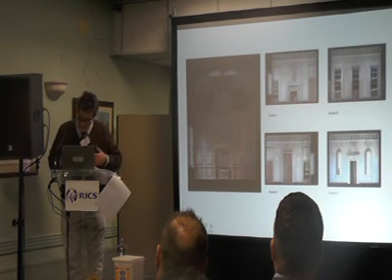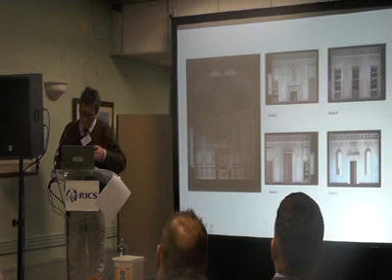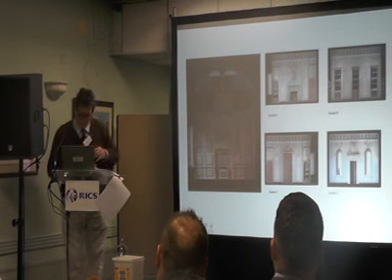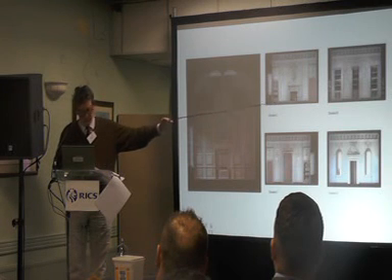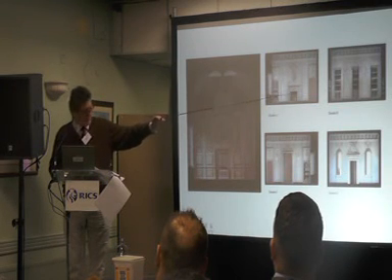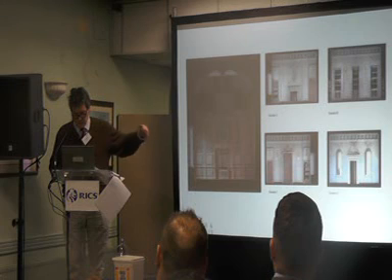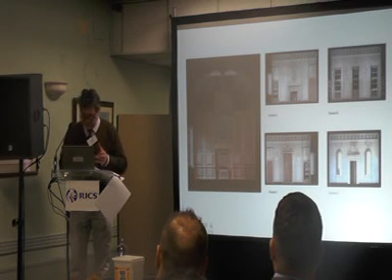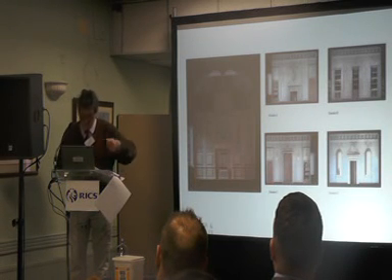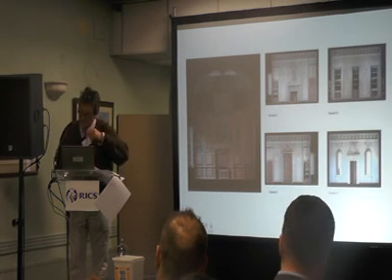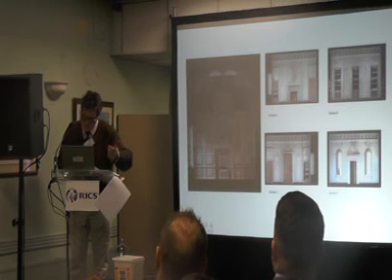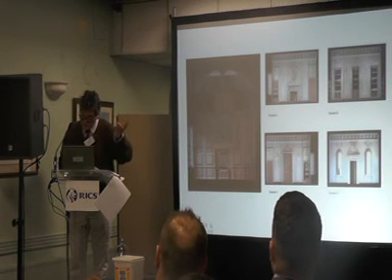If we scan that in 3D before we start work, we've been working above these plaster rooms. We've been doing hot works, wet works, and heavy structural works. And if we lose a piece of that plaster, we can send a piece of our scan to someone who's got a 3D printer. They can print it in plastic. We can put a latex over it, get a resin, get a mold out of it, put our plaster in that. We can actually put our piece of ceiling back exactly as it was.